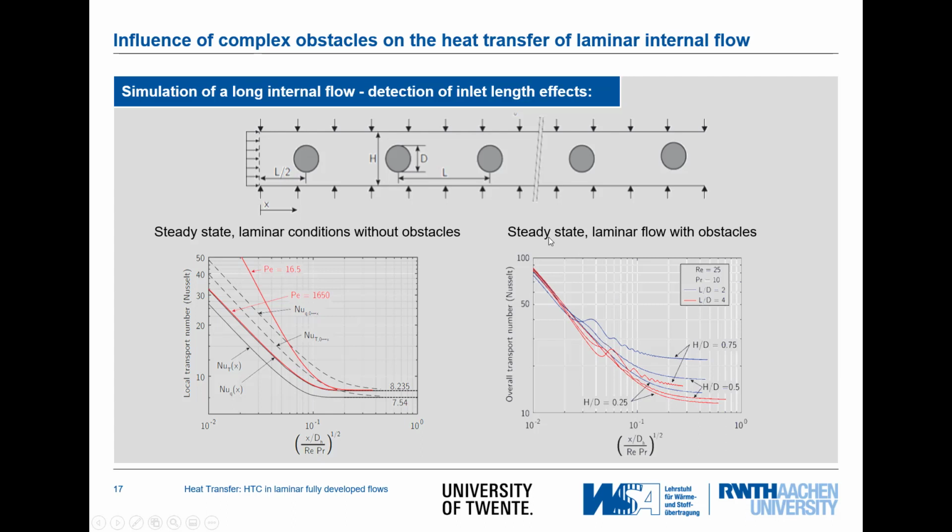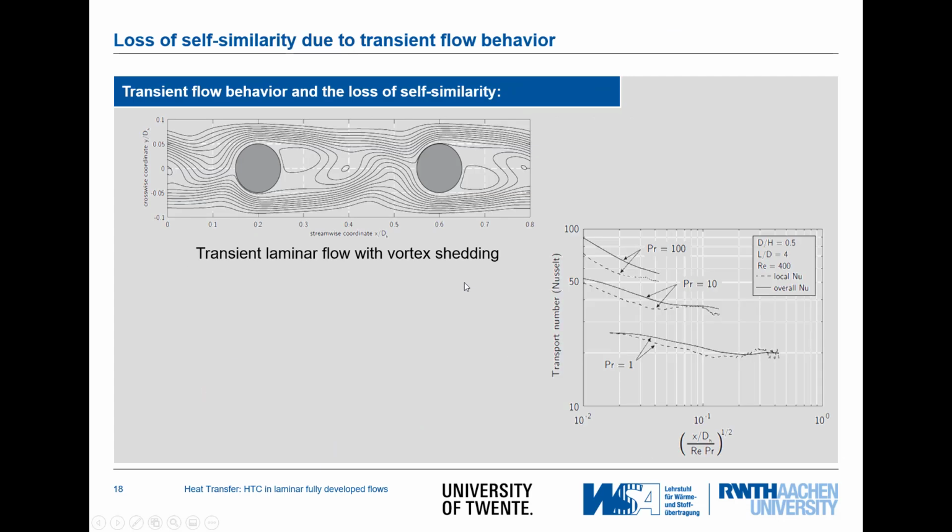So you see there is a chance that the heat transfer coefficient is not severely affected, at least the behavior, but if we increase the fluid velocity and it comes to the formation of vortices, this plot here is now an instantaneous plot of the velocity. There is a vortex shedding off on the left side here and here on the right side. And if we go further in time, then there is a vortex shedding off here on the lower side and here on the upper side.